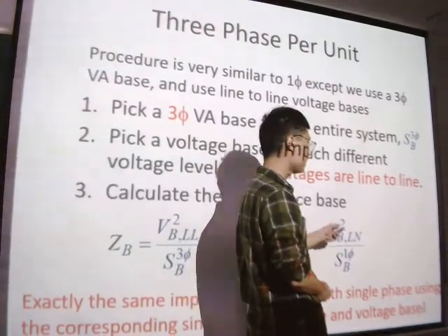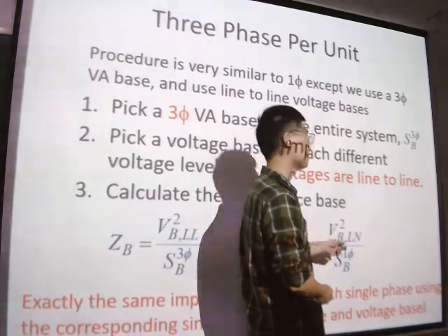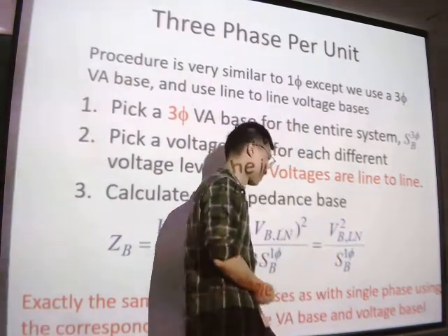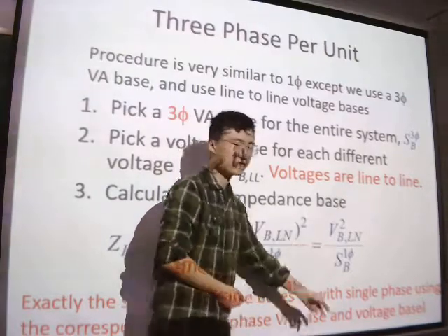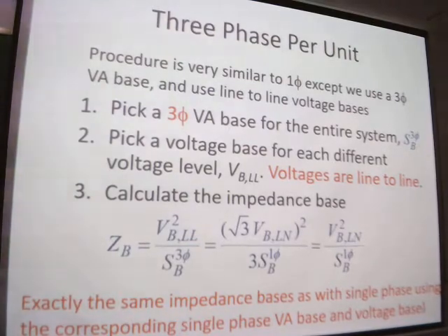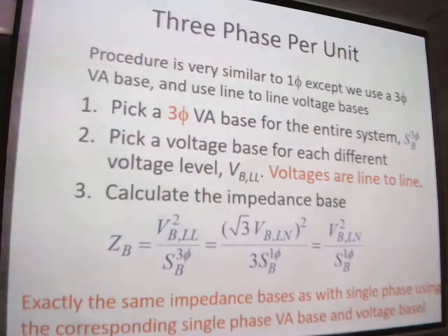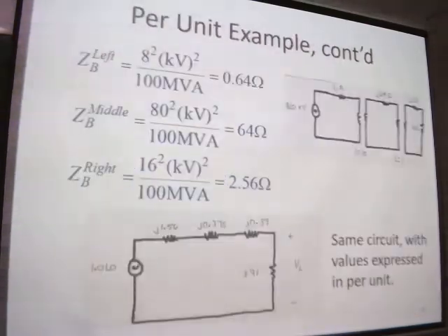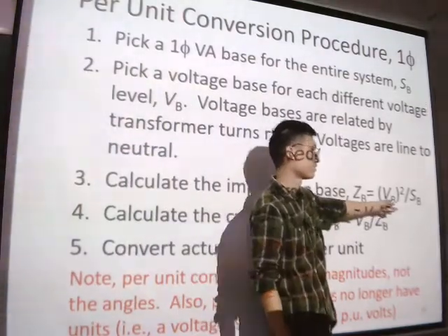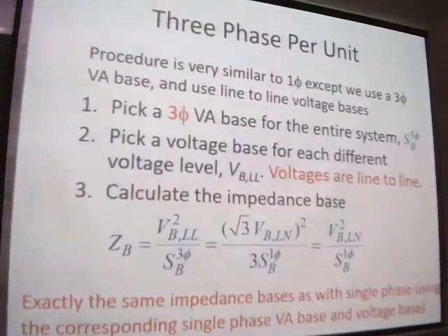So we'll get the phase voltage base squared divided by the complex power base of one phase. So you can see it's actually identical with the single-phase expression.